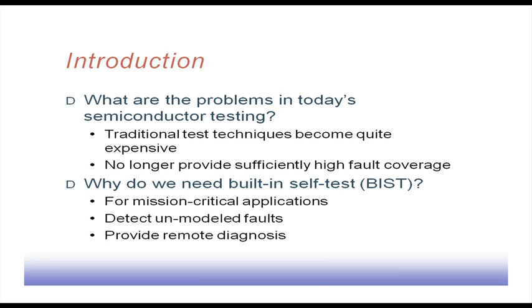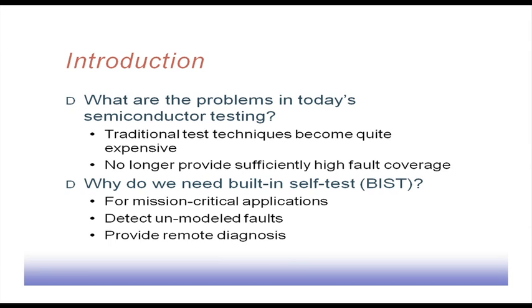So the detection of unmodeled faults becomes an important issue. Traditional test pattern generators are targeted to a particular fault model, say stuck-at fault, bridging fault or delay fault. The test patterns generated by them are suitable for those fault models only. So if there are some unmodeled faults, it is unlikely that those test patterns will be able to detect them. So this is another problem.